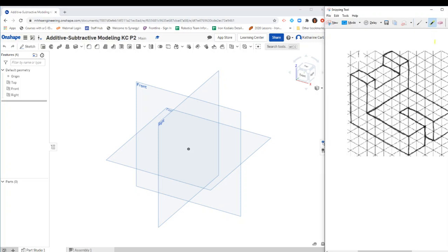The way I'm going to approach it is this front face right here that I'm highlighting in yellow. If I draw the outline and sketch using line tools and or rectangles, that shape, then I can go ahead and extrude it back, okay? And then what I will need to do is draw rectangles here and a rectangle on the top here, and I will have to cut those out, okay? So that's how we are going to be approaching it. All right, so let's get started.